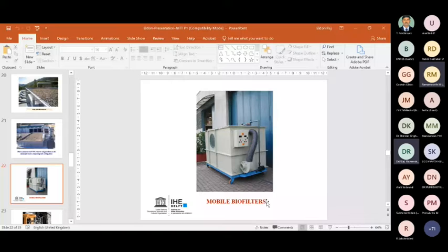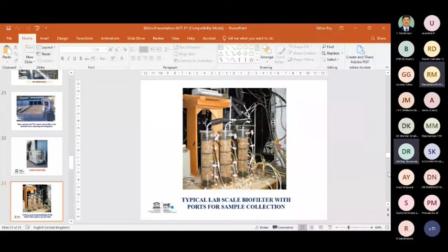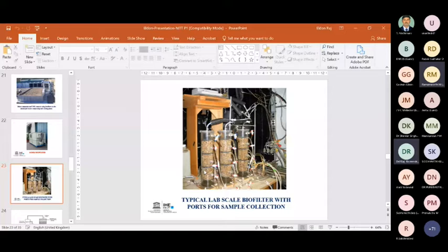These are all at the full scale, but at the lab scale, if we want to do research here, we don't go for such massive scales, whereas we go for a very simple system that is made of glass or acrylic. And in those column type of reactors, we pack them with a packing material like compost, wood chips, wood bark, and we inoculate the biofilter with biomass that is usually taken from an activated sludge process. Okay, so the wastewater treatment plant sludge contains a wide variety of microorganisms, and in my opinion, they are the ideal microbial inoculum for a waste gas treatment system. You can take them, you can mix them with the packing material, and you can have them within the biofilter.